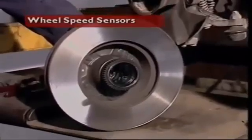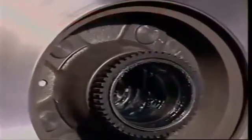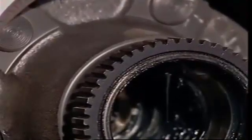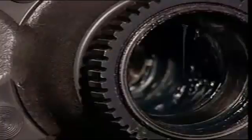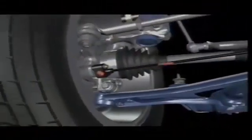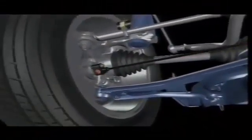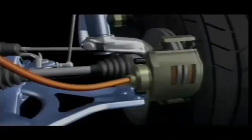This section examines wheel speed sensors. A wheel sensor consists of a toothed rotor that rotates with the wheels and a pickup. As each tooth of the rotor passes the pickup, a small voltage is induced in the pickup. These pulses are sent as input signals to the electronic control unit, which processes them to operate the hydraulic control unit.